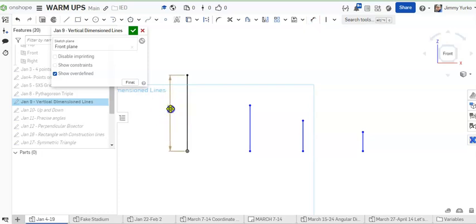It is important that when you place your dimensions, you place them next to the lines, not on the lines. That's really hard to read. And make sure the number is not on the arrowhead because that's hard to read. So this is the best place to put it. And we're going to do the next dimension. That's 1.5 inches. And then do it again, 1 inch.